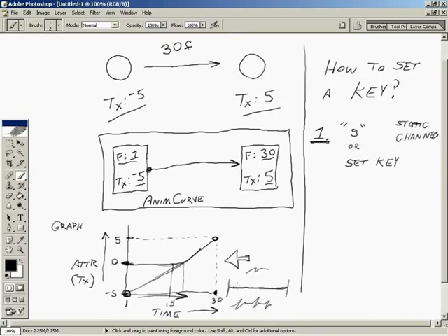And then you may have keyframes sitting on this flat line, like such, right? The value does not change over time, but Maya has to process this information. If you look at that graph that we've drawn out, a flat line would mean that the exact same value is being held over an extended period of time. The problem, though, is that since we actually have these keyframes, we're causing a calculation for Maya to have to read, even though no change is taking place.